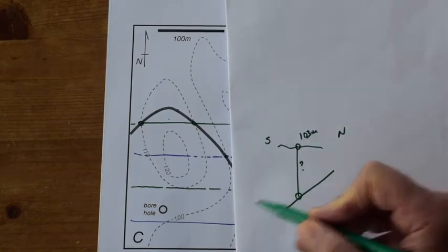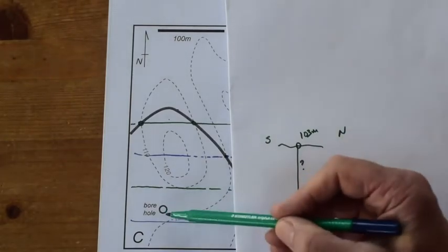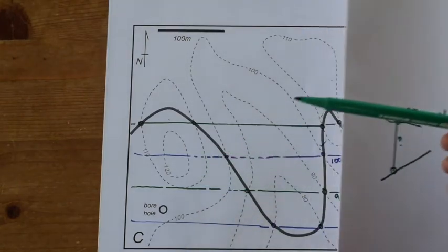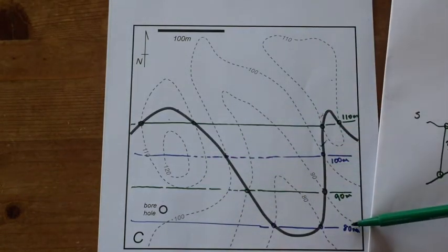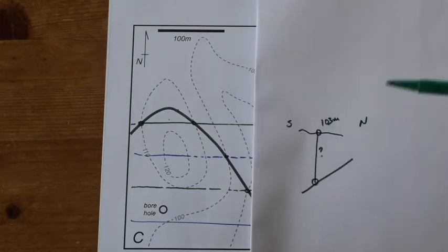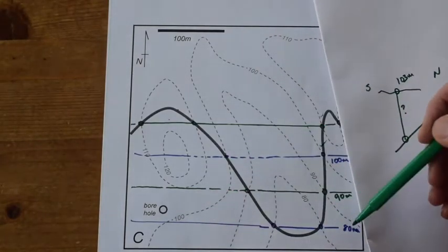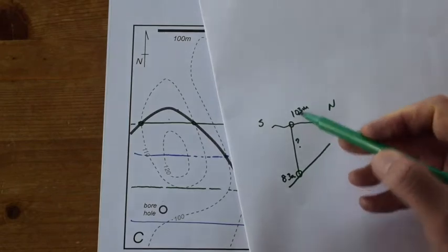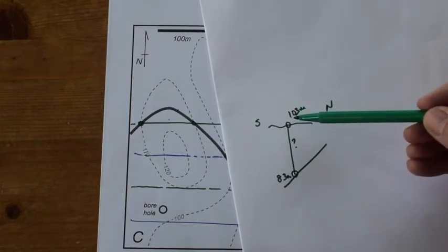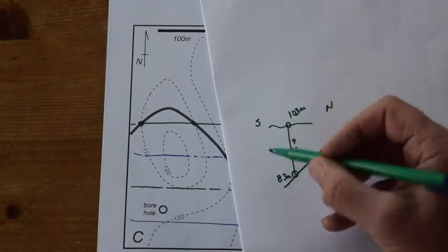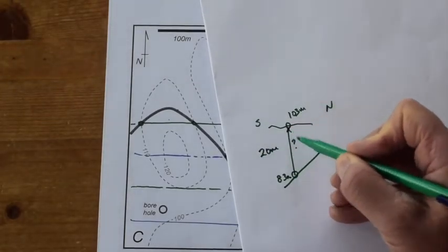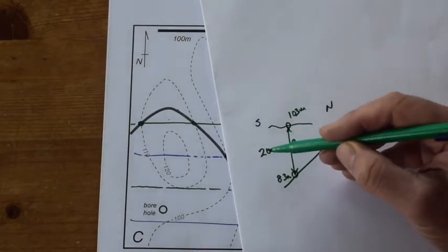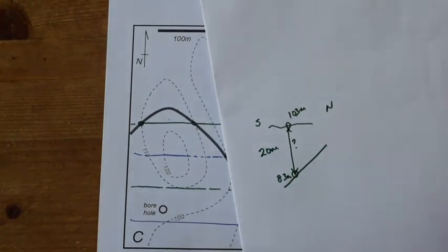And in the borehole down in here at the bottom, the boundary would be somewhere between the 80 metre contour and the 100 metre contour. It's closer, if anything, to the 80 metres. So let's say it's down at 83 metres here. So that is our borehole setup, and the difference between these 2 is clearly 20 metres. So that is the depth in our borehole to intersect that horizon. That's how deep we have to drill down to intersect the horizon.